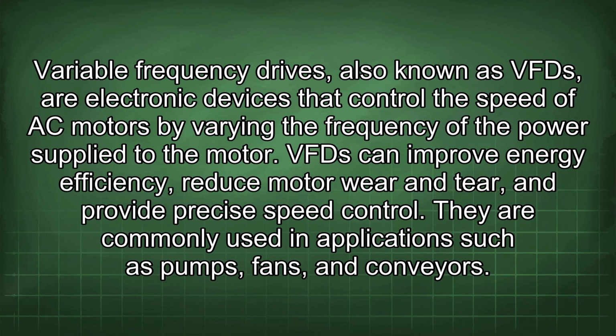Variable frequency drives, also known as VFD, are electronic devices that control the speed of AC motors by varying the frequency of the power supplied to the motor. VFD can improve energy efficiency, reduce motor wear and tear, and provide precise speed control. They are commonly used in applications such as pumps, fans, and conveyors.